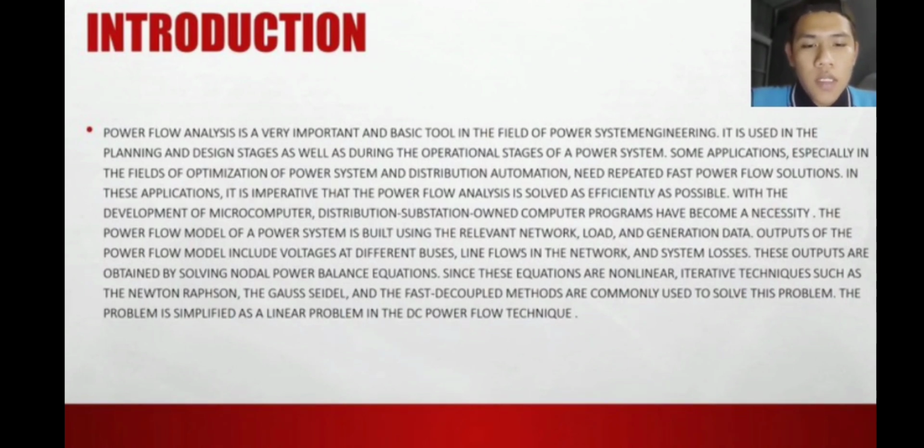Since these equations are non-linear, iterative techniques such as the Newton-Raphson, the Gauss-Seidel, and the fast decoupled methods are commonly used to solve this problem. The problem is simplified as a linear problem in the DC power flow technique.